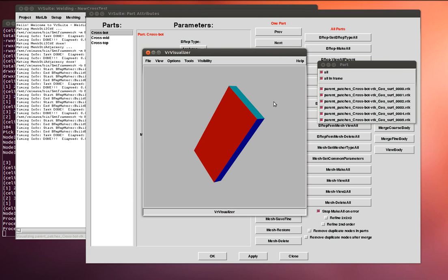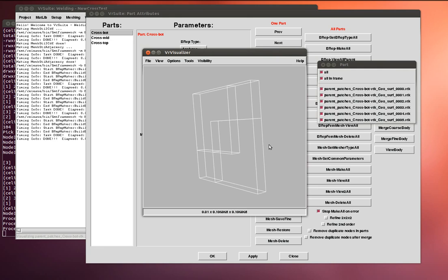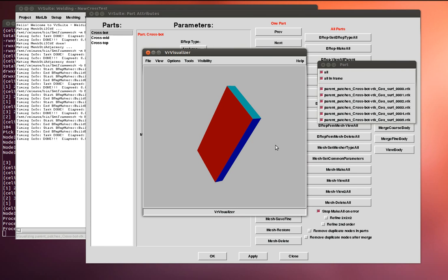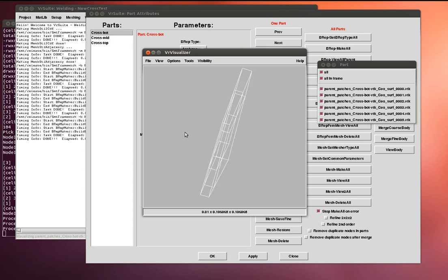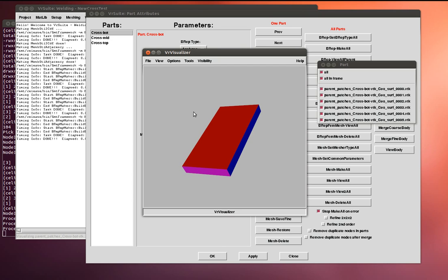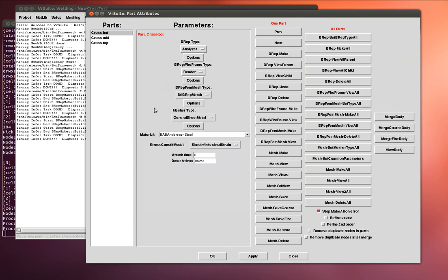Now usually we want to mesh the large part. This software was originally intended for sheet metal parts, and so there are many things that are set up to make sheet metal meshing easy. So what we often do is mesh the largest patch and extrude it to the next largest patch, which is convenient if your thing is similar to sheet metal. That's the BRep. We have a number of other items here that I'll ignore for the time being.